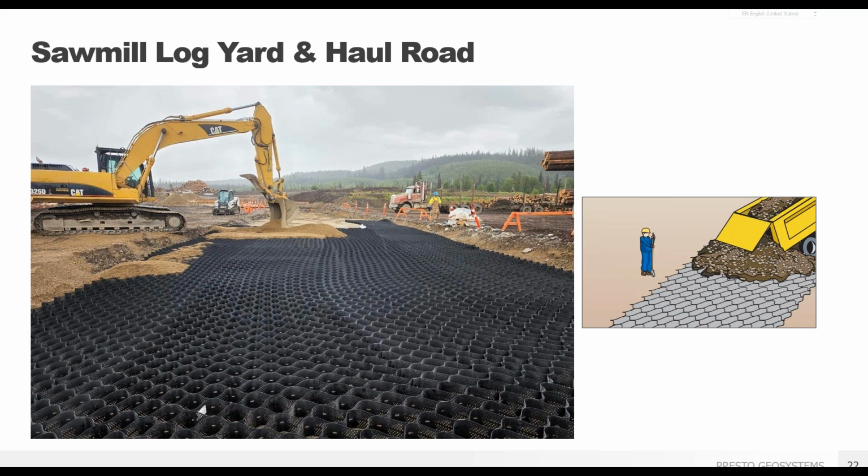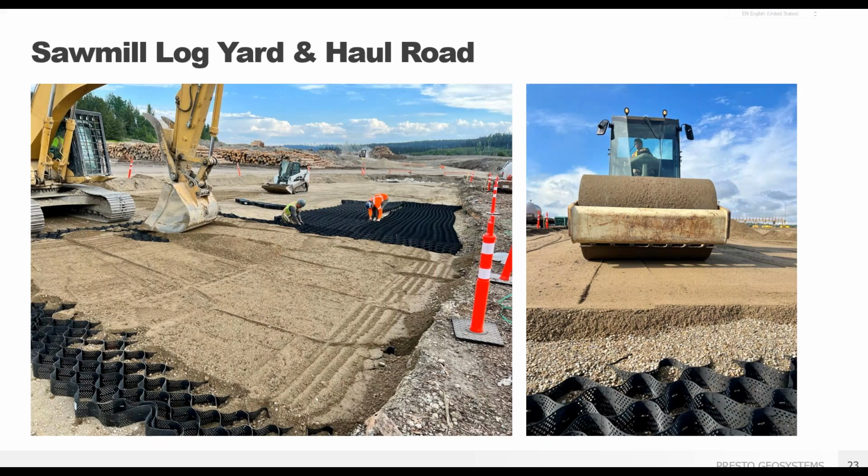Here we see the infill being placed, and good technique is to limit the drop height to 1 meter or less, about 3 feet, to ensure the empty geocells don't fold over and are evenly filled. GeoWeb created a smooth platform that eliminated rutting and constant maintenance, and both the project owners and the installers were pleased by the ease and speed of installation thanks to AtraKey connectors.